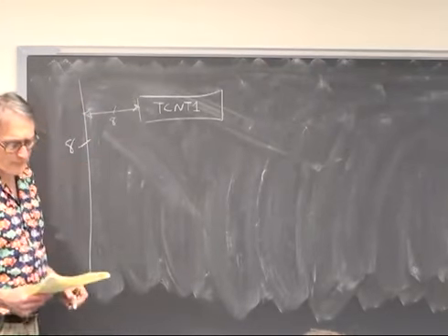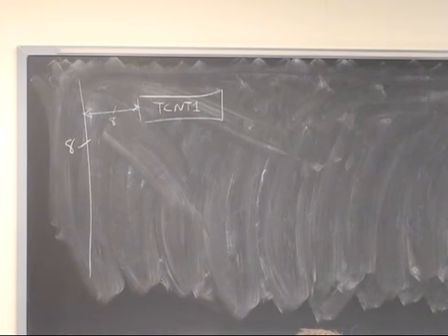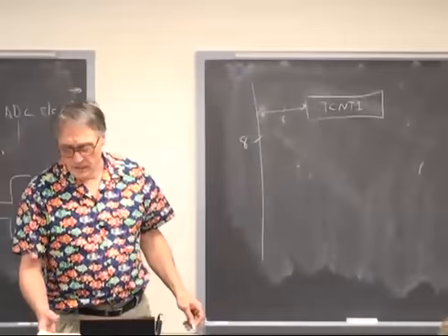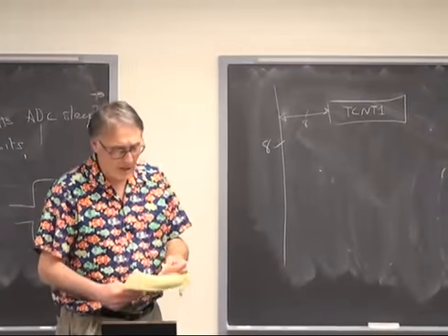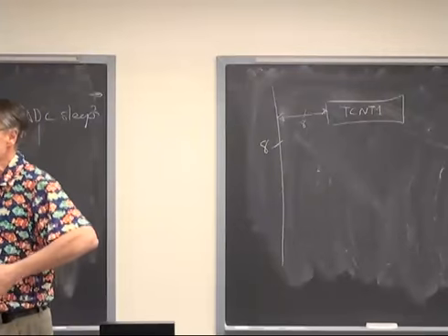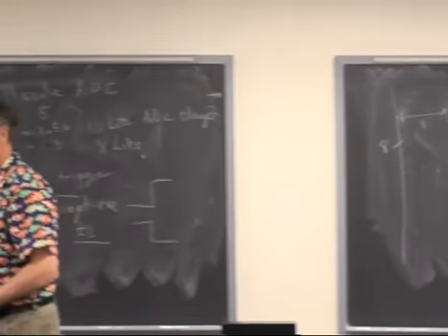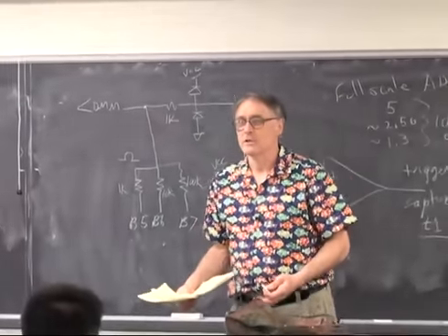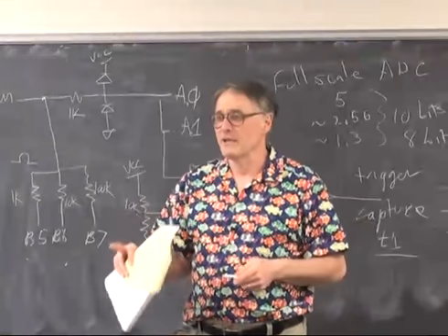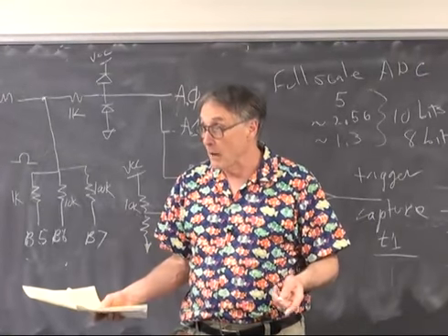This means that you have to take 2 bus cycles to write the 16 bits to TCNT1, which is the timer 1 timer. And because it's time that we're interested in here, you want to make sure those 2 writes or reads appear to be simultaneous. Right? You can't read a byte, wait a few cycles, read the other byte, and expect to get a correct time.